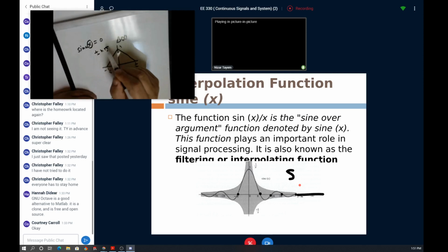Yeah, side lobe, sorry, not loop. So this is mainly where most of the signal will be. This is not good. It's undesired, especially when we talk about digital communication. If I'm sending a bit stream of data, the pulses will overlap with each other. One way to get rid of these side lobes is using an equalizer. But this is how the sinc function looks like.